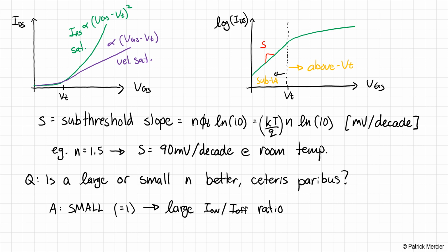Now, of course, we don't use BJTs all the time when we're building digital systems, for a very good reason. One of those reasons is that they have this current that has to go through the base of the device, which doesn't nominally exist in a CMOS transistor. In addition, we've gotten very good at miniaturizing each CMOS transistor such that we can fit a very high density of transistors in a small area. And for these reasons, CMOS transistors have won the digital logic compute space by far over any bipolar type of technology.